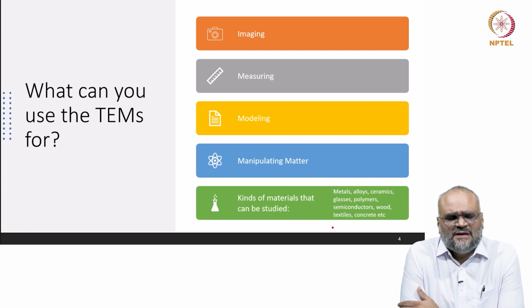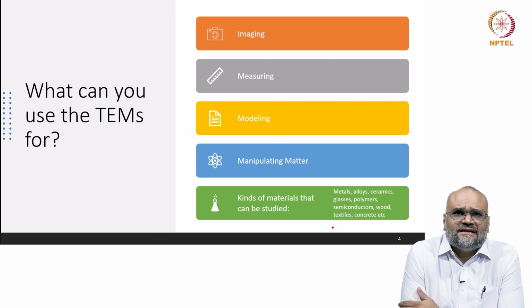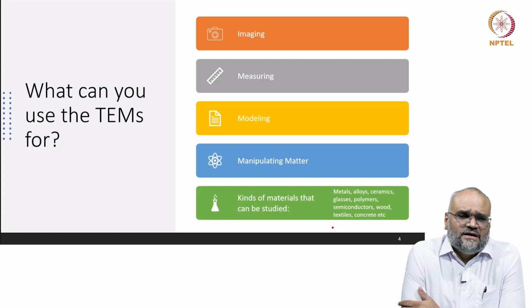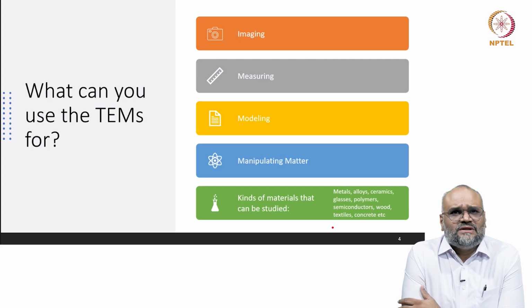And by combining the imaging and the measuring and analytical techniques that you use, you build some information on the structure property relationships of a material. So this is where your modeling aspects come in. There is of course something called crystal structure modeling, and also solving the structure or atomic structure of a material through focus exit wave reconstruction. And there is a lot of modeling done to even model the imaging and the contrast mechanisms in a material as well. So there are various aspects of modeling in connection with TEM.